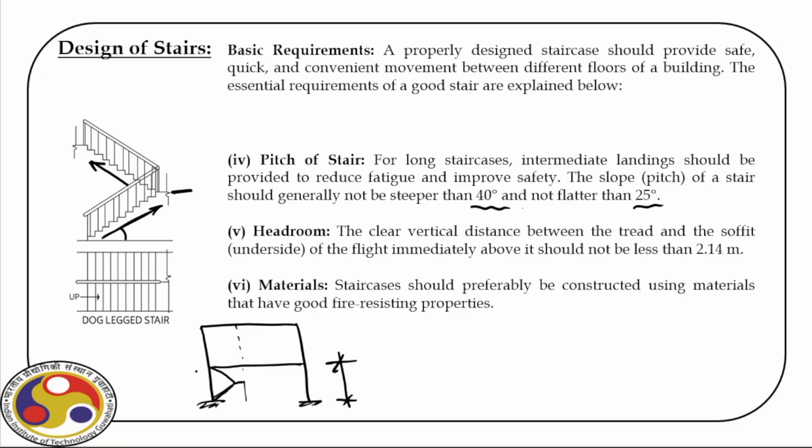In that case, this stair covers the entire height, but we should provide a clear vertical distance between the tread and soffit. As you can see here, if we need to enter from this place, this is the height because this is the half landing. So we should keep sufficient space for movement. Normally there is again a guideline of 2.14 meter.